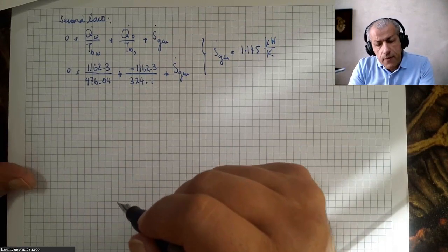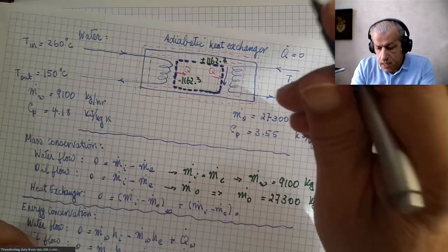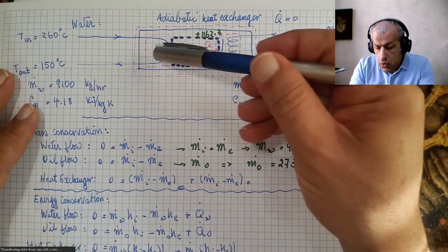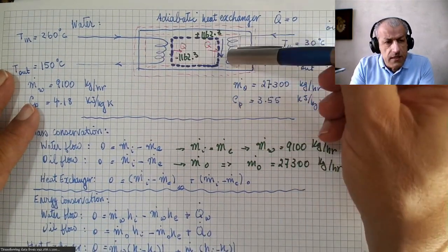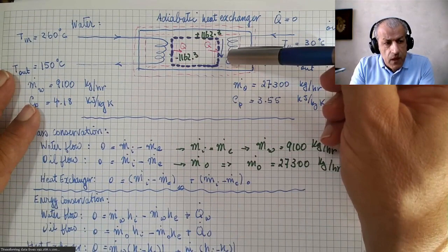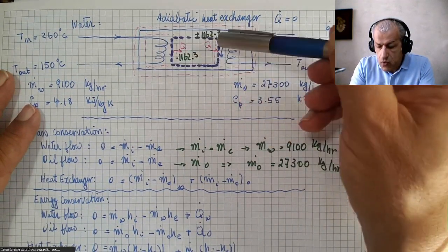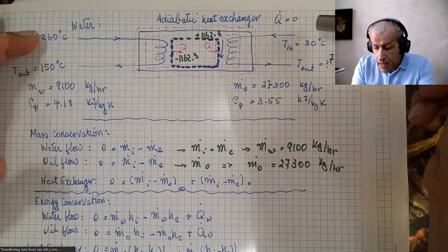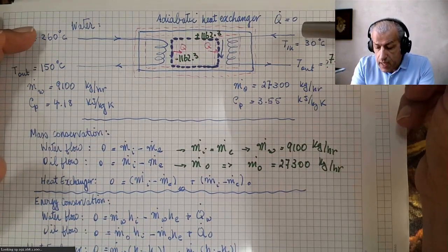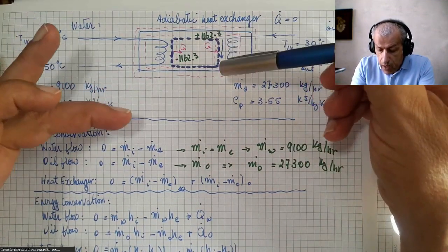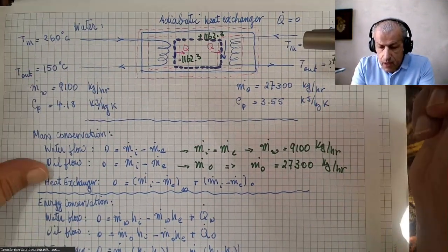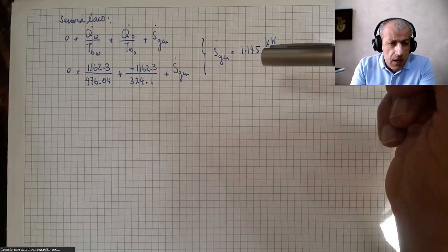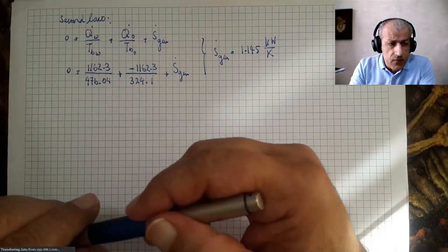And the final point that we need to discuss is that these are two temperature sides to the heat exchanger. We assume the parallel flow, so both sides would enter, move parallel, and exit. I mentioned that there could be a counterflow heat exchanger, but let's see how that would look.